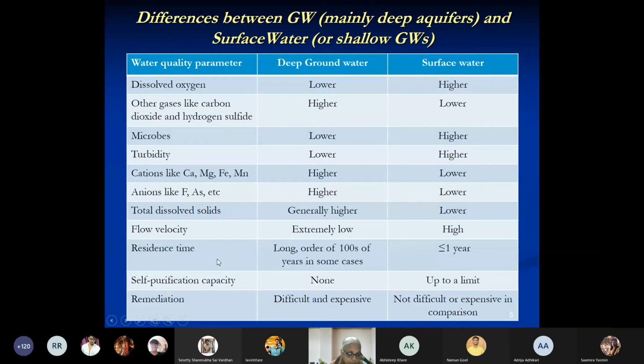We looked at the self-purification capacity of a river and we saw that the DO level will come back to normal after a given amount of time. So within a limit, this is okay for surface water as long as we do not exceed the self-purification capacity of the river. But groundwater has no self-purification capacity, zero. There is no way, because it's not in contact with the atmosphere. There is no way for the groundwater to purify itself. It's just not going to happen.